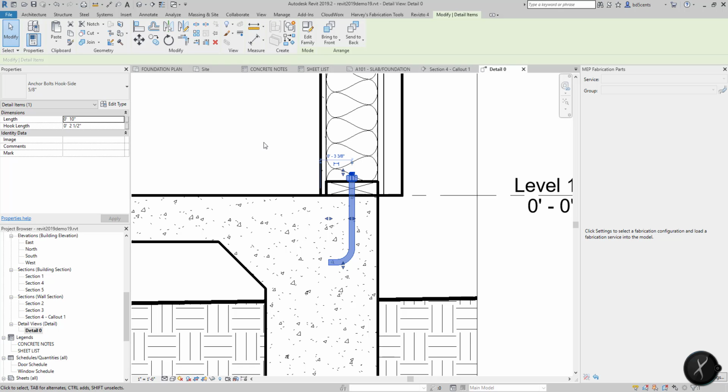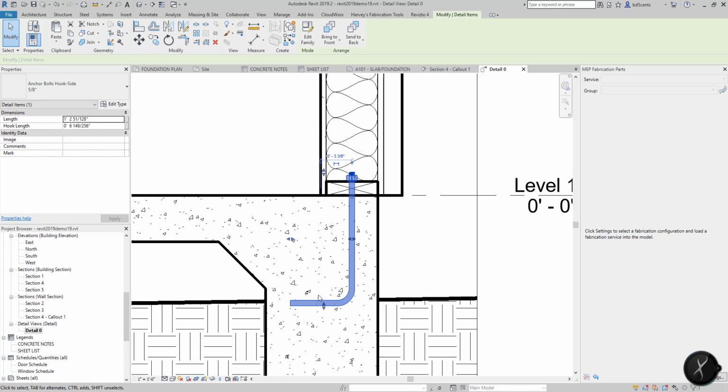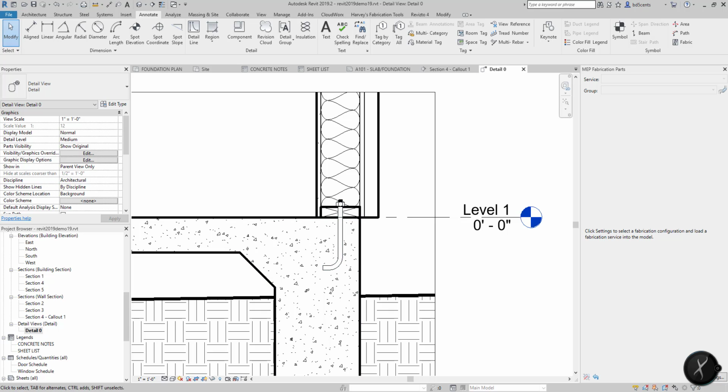So I showed you how to mirror it. I didn't show you these bars, but you can adjust the length with these bars. So it's a parametric two-dimensional detail, and you can really adjust values and get it to work the way that you want. You can create your own parametric families of these details as well, but we're not going to get into that for the extent of this lecture. But at least you have an idea of how to adjust these values to get them to fit within the confines of the way we're drawing them. So I'm going to place these in there. These are super powerful tools.